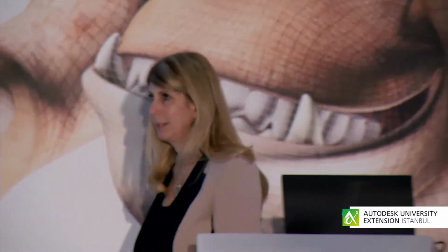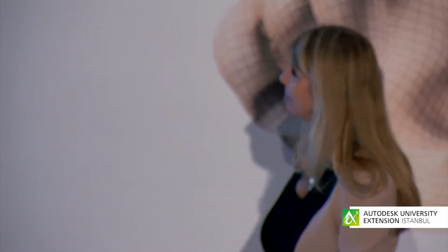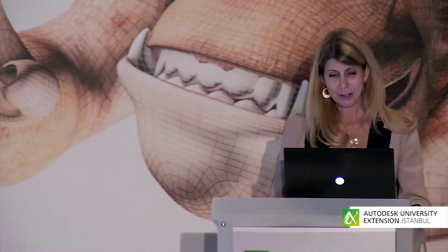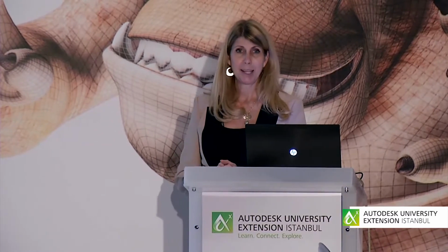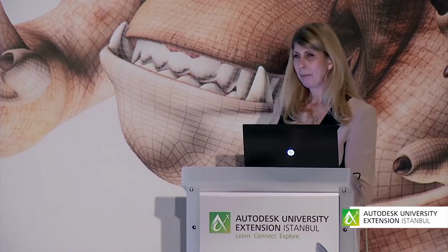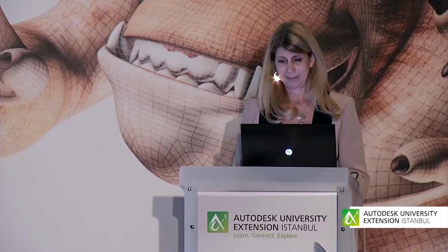Go away. But at the top of the screen, you'll see that it automatically modified the ribbon to only give me the commands that have to do with the PDF. So when you double click on certain things in the screen, AutoCAD automatically changes for you as long as you're using the ribbon. If I come in here and I double click on hatch, you will see that it gives me the ribbon just based on hatching. I love that. That saves me time. I'm a very lazy AutoCAD user.